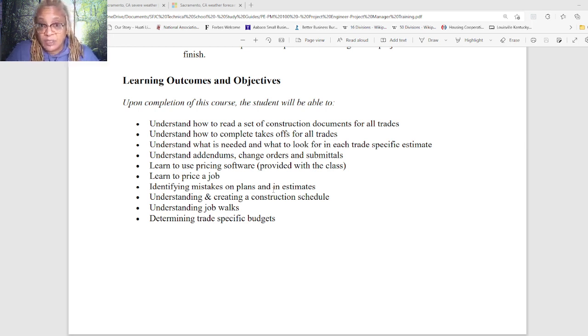I mean based on industry standards. So as a project manager, you have to know how to go to a central source to put in how many square feet of wall you're going to be building, or how many squares of roofing of a particular type is going in, and you should be able to determine how much time that's going to take, and you usually get that information from a really good cost book.